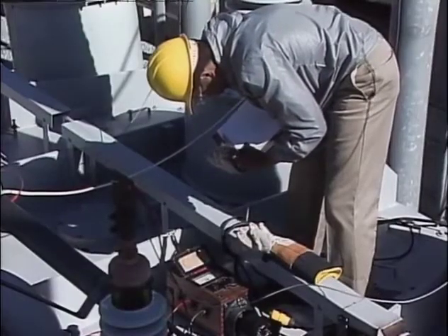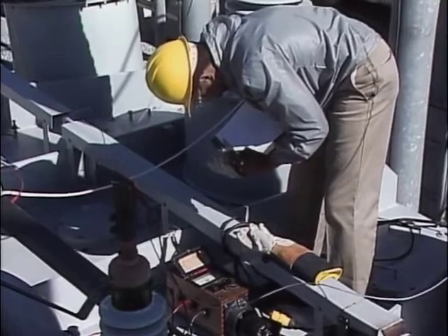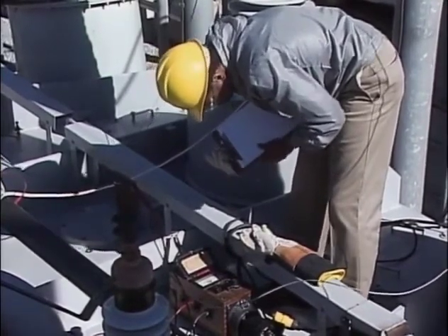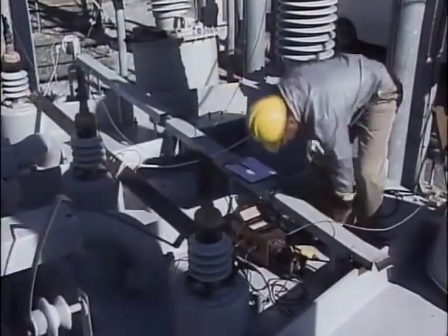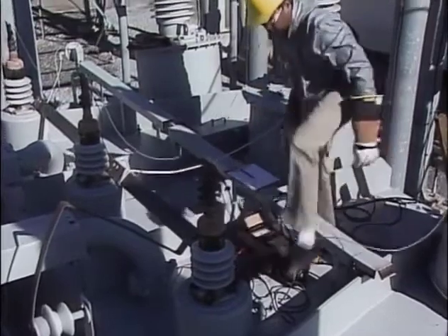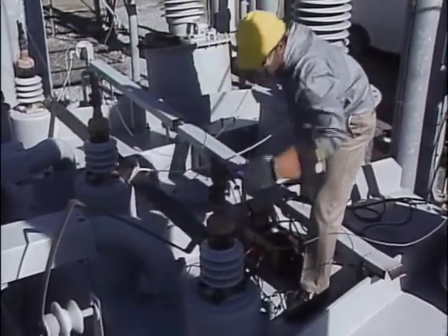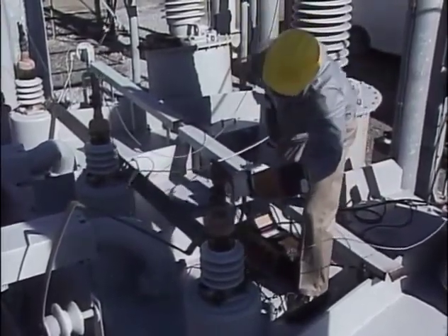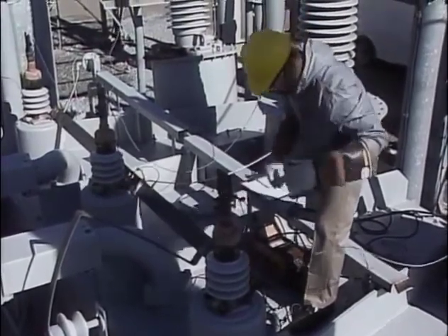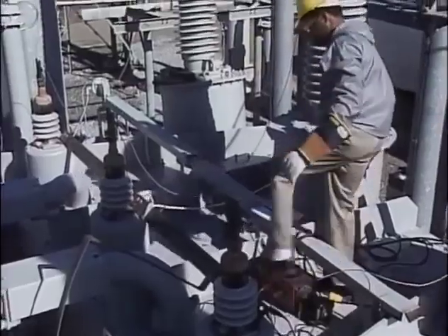After the megohmmeter is turned on, the resistance indication is allowed to stabilize. Then the resistance reading is documented. To test the insulators for the next phase of the reactor, the megohmmeter is turned off. The ground is reconnected from station ground to the neutral terminal, and the voltage lead of the megohmmeter is moved to the neutral terminal for the next phase to be tested.